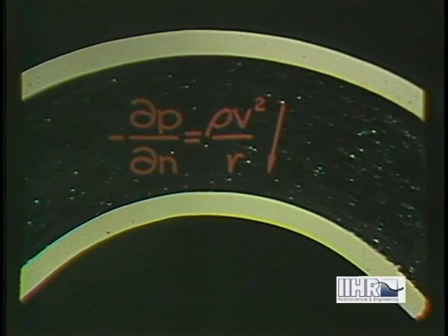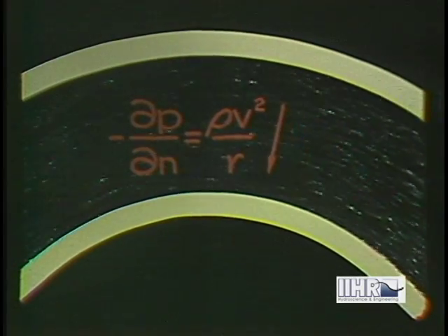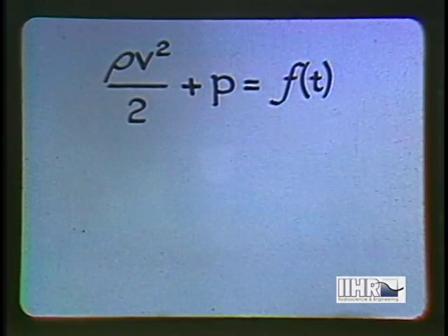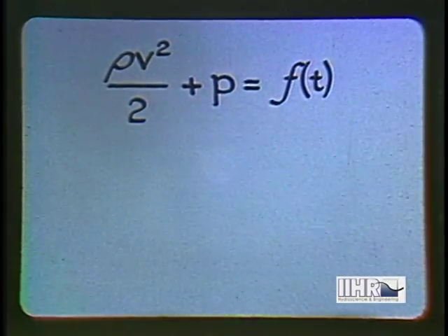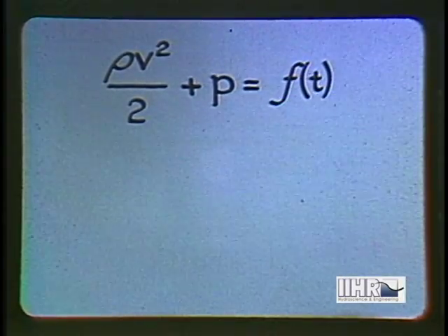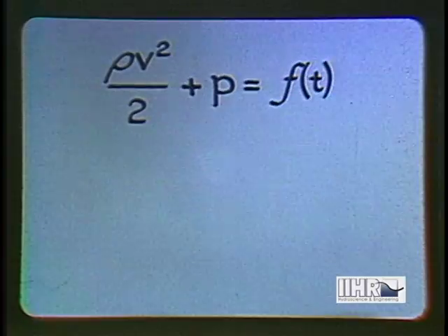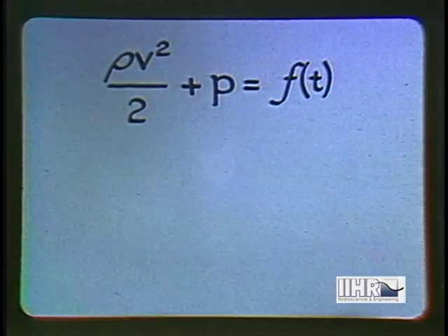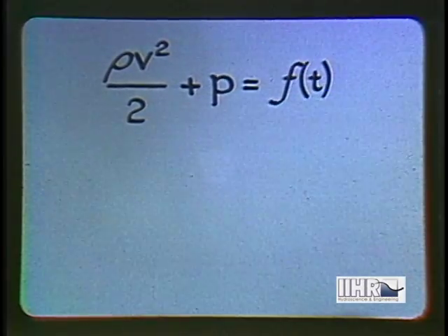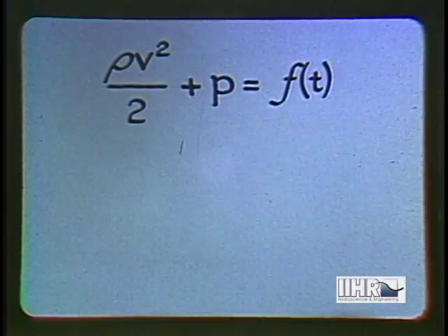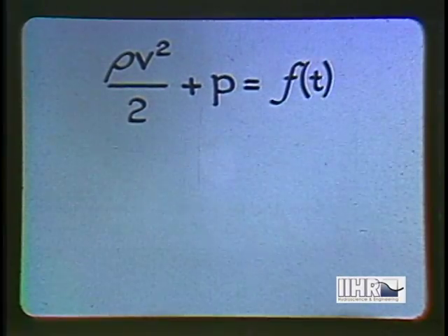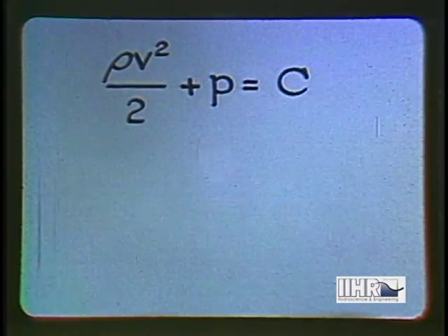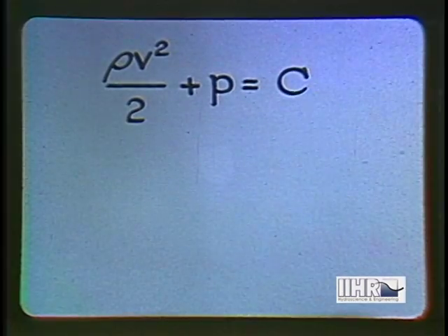We shall discuss a few cases of unsteady motion at a later time. For the present, let us note that for steady, irrotational flow, the equations of acceleration can be integrated to yield a very convenient and significant pressure-velocity relationship. This states that at any instant, the sum of what is sometimes called dynamic pressure and static pressure must be independent of location, but not of time. This sum will be independent of time as well, if the overall pressure load does not vary.